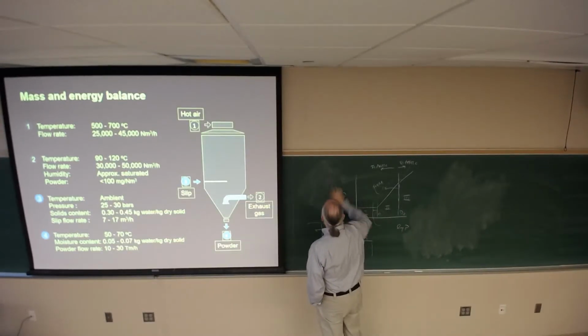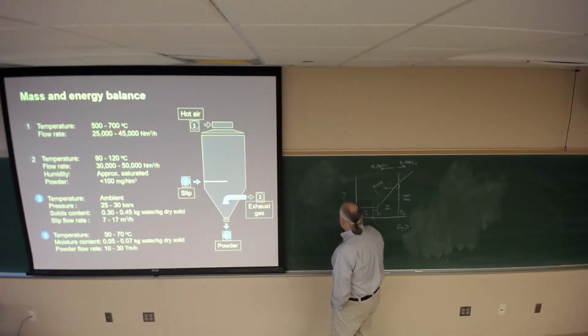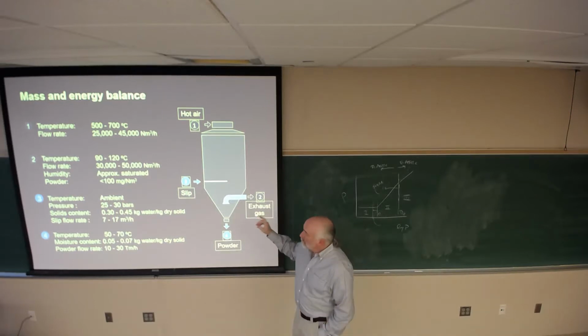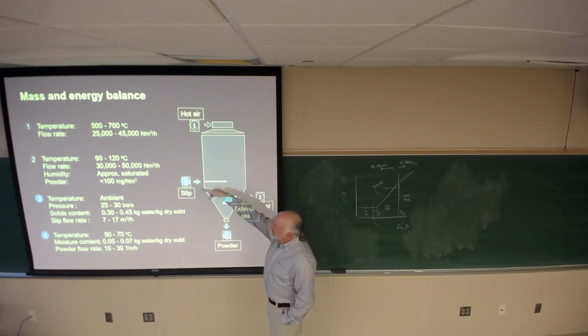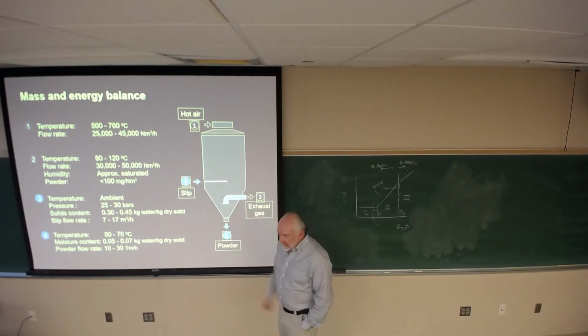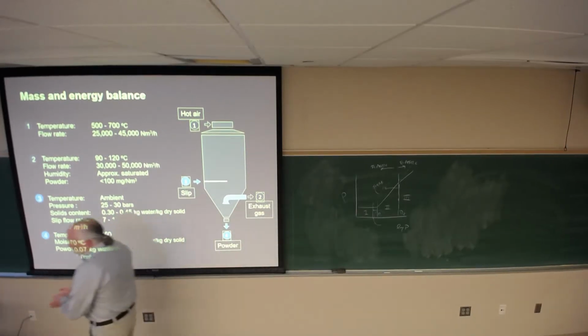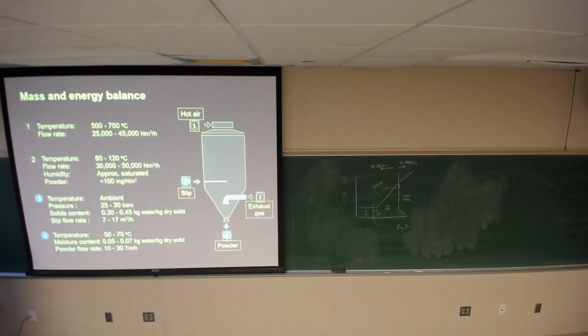And then, this is the spray dryer. So it's quite large. These values are real, and there are larger spray dryers. The thing about spray drying is that nobody, and I don't mean just me, I mean nobody has figured out scale up. You're on a laboratory scale, you go to a larger spray dryer, and then you have to refigure out your conditions. So if we go back a couple slides to here,